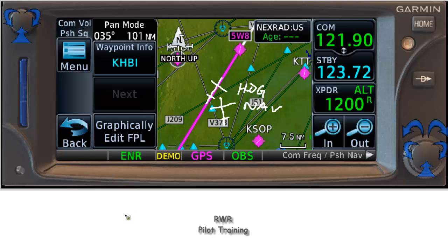So just rough order of magnitude, when we're looking down here below the box now, when we're flying along and we get to a point which is 5 miles away, we need to be at 1,500 feet, and this is obstacles notwithstanding. So you could use terrain avoidance or visually separate ourselves from terrain and obstacles.